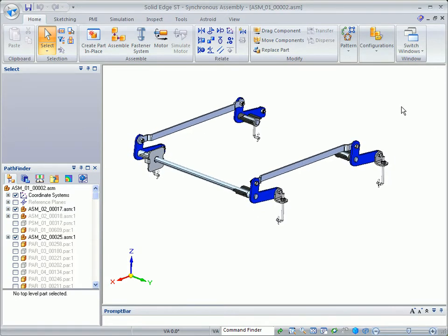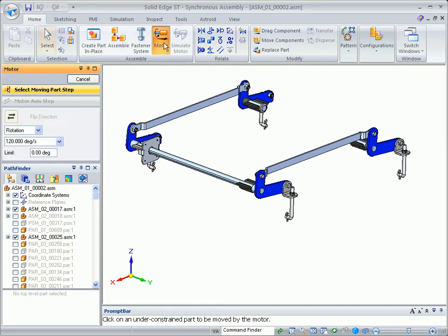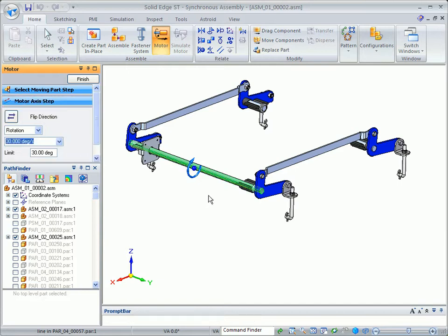And in order to animate that, we're going to first apply a motor to this front bar. And let's go ahead and use 30 degrees a second. And we'll also add a 30 on the front for limit, because we want to limit its motion to 30 degrees. And then we can identify the front round bar, and then you'll want to set your rotation clockwise.